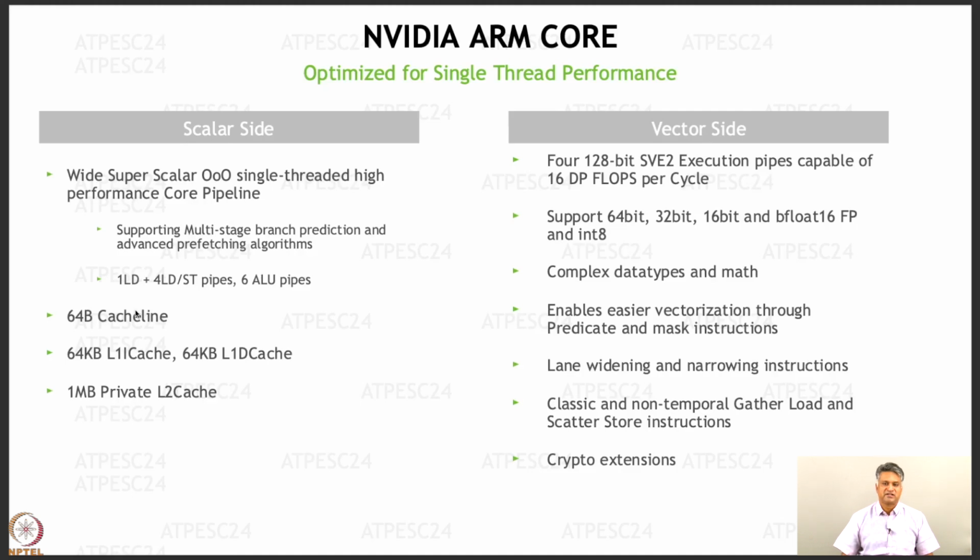It supports 64-bit, 32-bit, 16-bit, and integer 8 operations. It supports complex data types and mathematics. It enables easier vectorization. It allows the lane widening and narrowing of instructions. It has classic and non-temporal gather, load, and scatter instructions. It also has instructions for crypto.